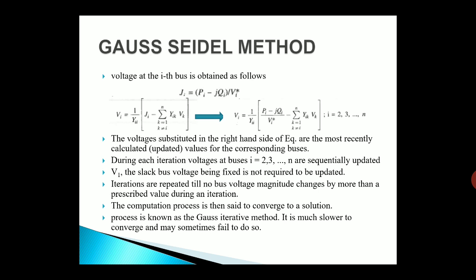Moreover, let me be clear that all these voltages are in per unit. So we start with a voltage of 1 per unit. So for, let's say, bus number 15, you get a value of 0.9, then you get 0.95, then again 0.951, then you again get 0.945. So now the value of the bus is not changing much. So around this value you can be sure that this is the value. Okay, so this is how we do it.